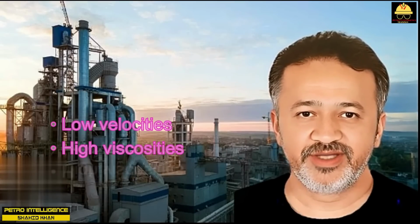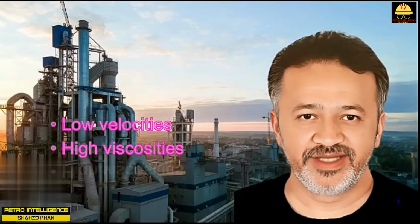Laminar flow is caused by two factors: low velocities and high viscosities. A low velocity for liquids is 2 or less than 3 feet per second. Velocities of greater than 10 or 12 feet per second may cause erosion of metal surfaces and should be avoided. A low viscosity is 2 or 3 centipoise or centistokes. Tap water has a viscosity of about 1 centipoise. A viscosity of ~50 centipoise is quite high. Warm maple syrup has this sort of viscosity.